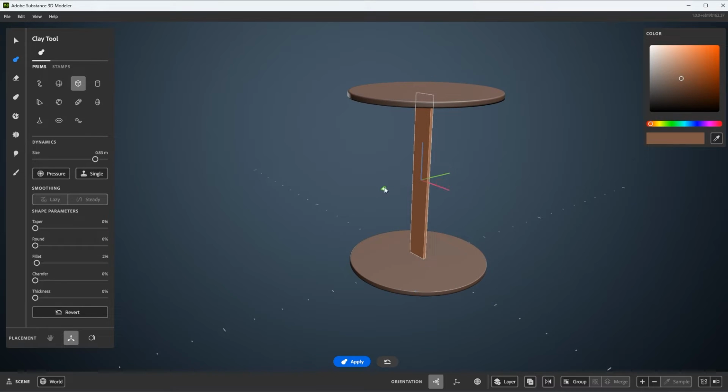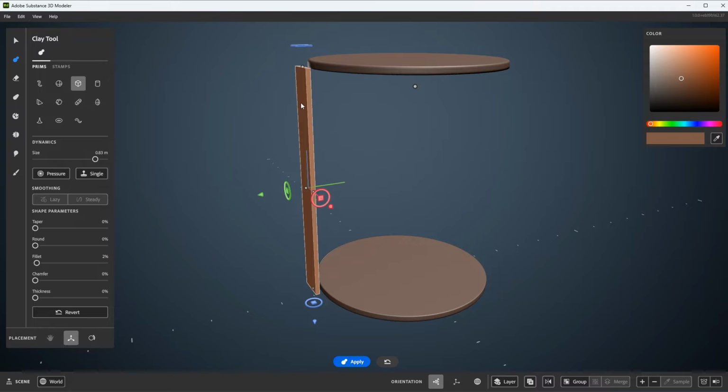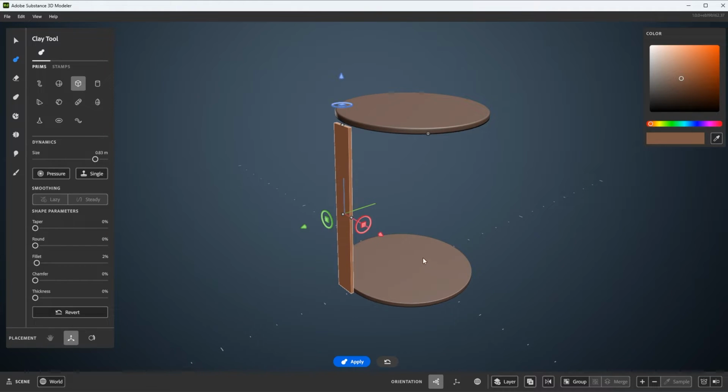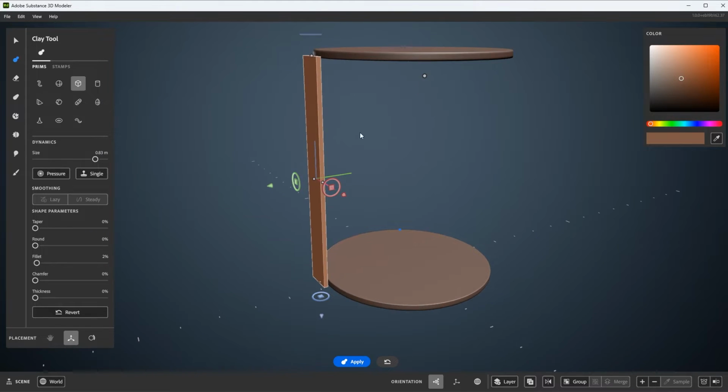So here I'll grab the Y axis and move it out from the origin, because when I do my repeat, which you'll see here in a moment, it's going to repeat around that origin point. In this particular case, because of the way I've constructed this barrel so far, everything is at the origin. So I can go ahead and just move this out.